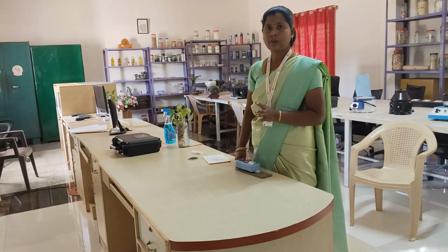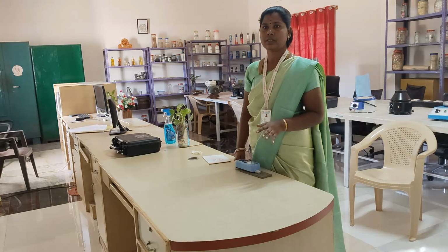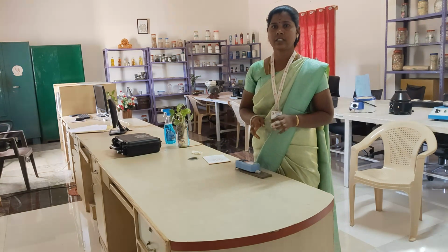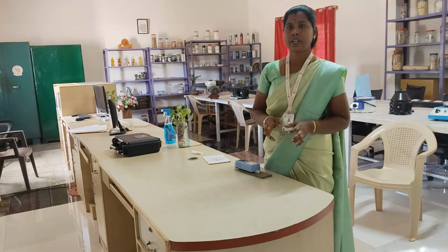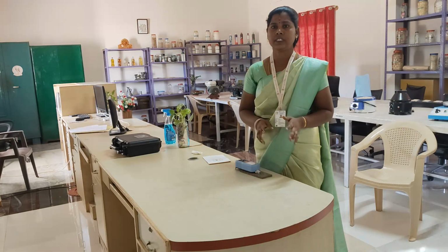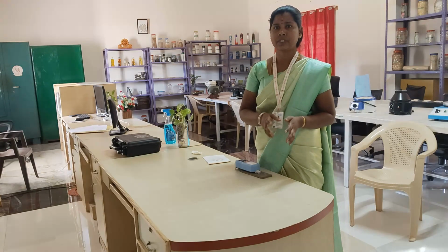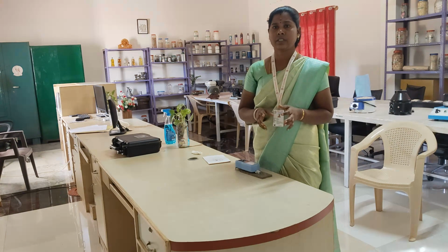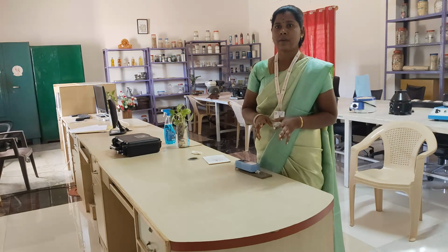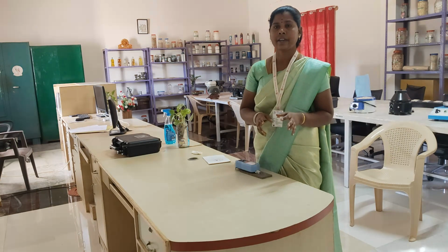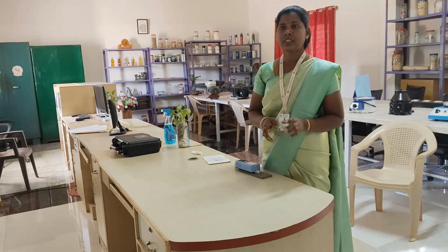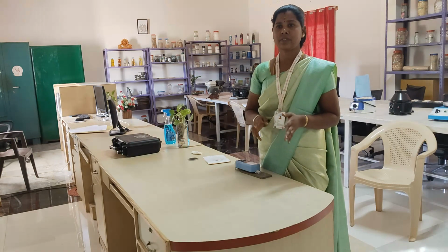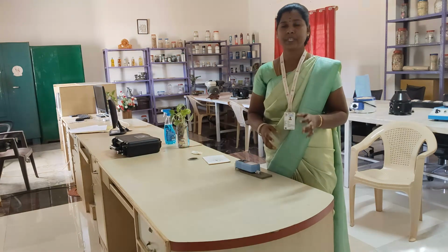When we compare the results obtained from both surfaces, we can clearly observe a significant difference. The polished granite surface shows a lower Ra value of 0.191, which indicates a smoother surface with fewer and smaller surface irregularities. On the other hand, the unpolished granite surface shows a higher Ra value of 2.767, indicating a rougher surface with more prominent peaks and valleys.